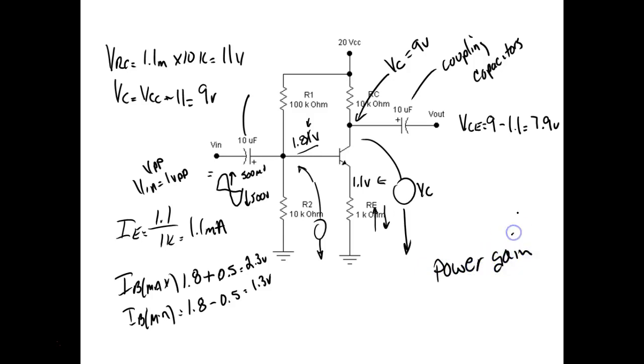Period. Now we can get power gain by getting a voltage gain, right? Or we can get it by getting a current gain, or we can get a power gain if we somehow get both of those. But understand, the guy is not creating a power gain. I mean, it can get more out than we put in, but we'll never get close to that, right? You understand that? Because of the efficiency of the amplifier. So that 20 volt VCC is the power supply. It's the guy that's providing the current. It's the guy that's providing the voltage. It's the guy that's providing the power.